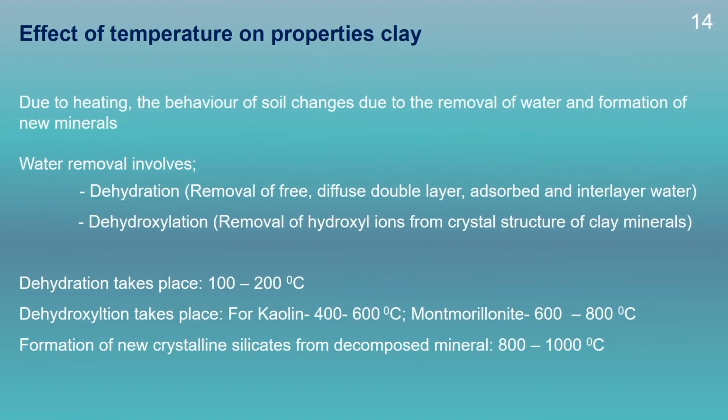Next, I will discuss the effect of temperature on the properties of the clay. Previously also we have learned that the diffuse double layer, which controls the behavior of the expansive soil, also gets affected by the temperature. And we know that there are three types of water present in a soil. One is adsorbed water, the second one is the diffuse double layer water, and the free water.